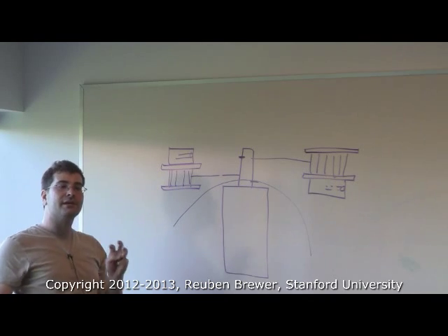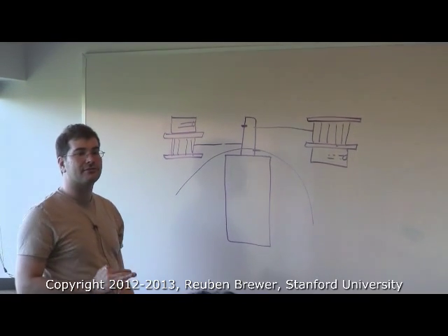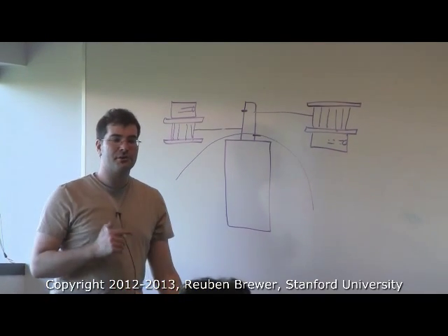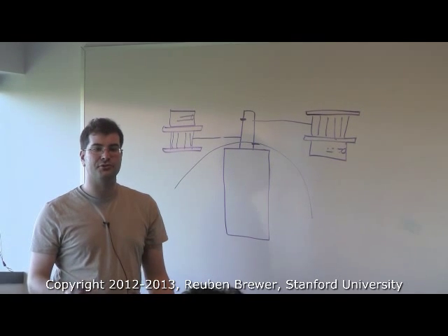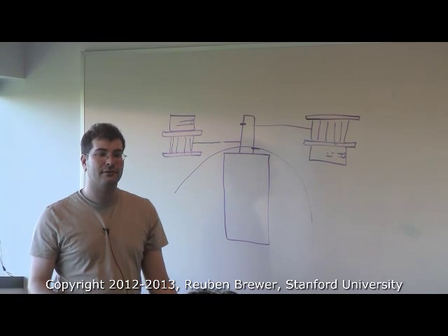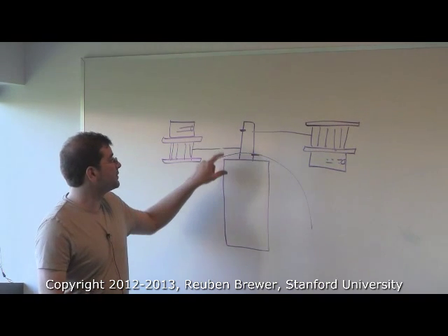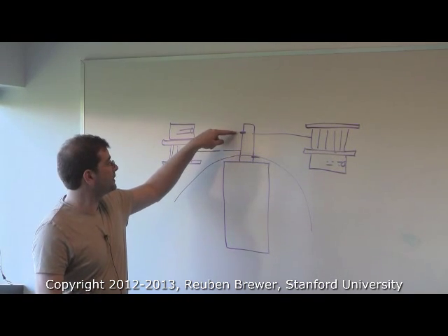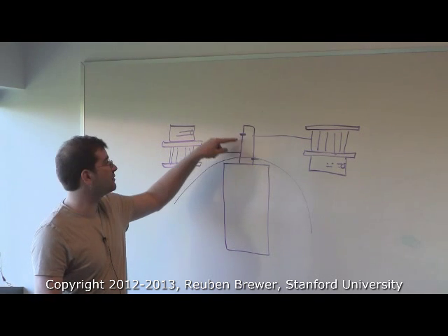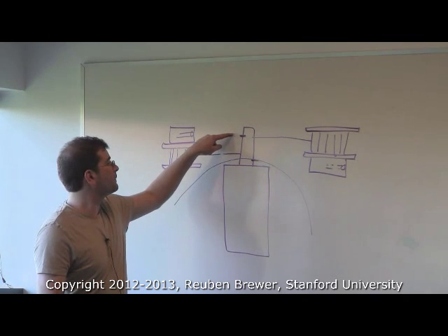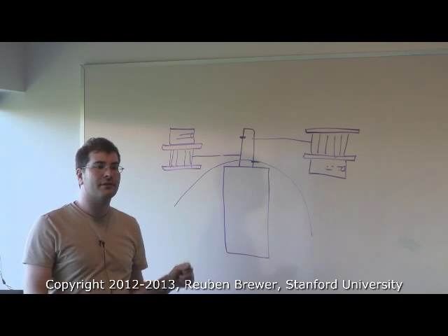Okay, let's back up for a sec. You can buy motors with flats on the shafts. Sometimes the motor you want doesn't have a flat on the shaft, so you Dremel one on. There's no way around that. Maxon hates making custom motors. So you're going to Dremel this. Do you want to Dremel to here or to here? You want to Dremel to here. Okay? Now, one other thing about set screws.